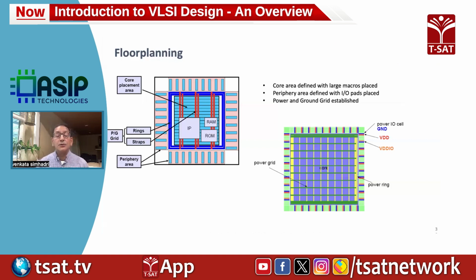So these are the two most important aspects of power planning: placing all the cells in the design, and designing the IO ring and power mesh, to make sure that you have a good start in completing the floor plan, and completing the place and route.